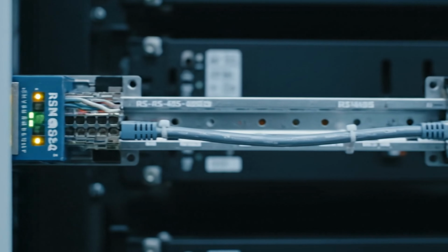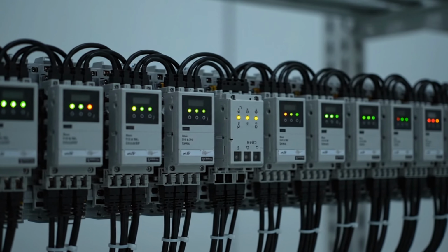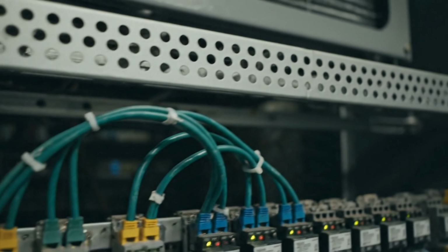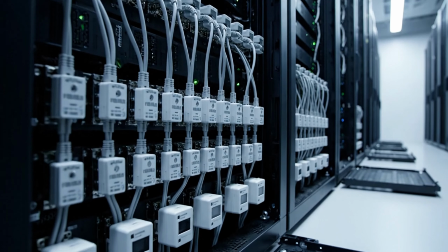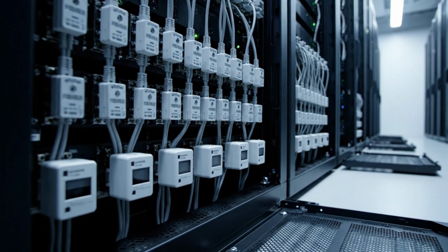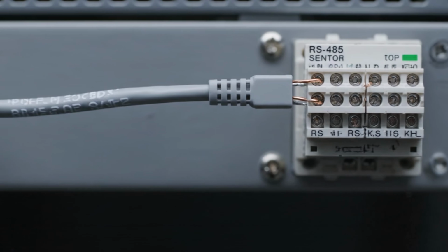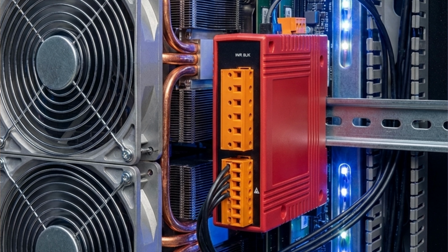So Modbus RTU is the one most people recognize. It runs over RS-485, it's simple, it's deterministic, and honestly, it's one of the most durable communication methods still used in industrial environments. I mean, there's a reason why so many cooling and environmental sensors still rely on it. Rack level temperature and humidity nodes, airflow sensors, leak detection modules, devices that are almost always deployed in large groups, tend to be built around RS-485 hardware. Even a lot of power meters used on cooling loads, like the kinds you'd see feeding data into a monitoring loop, still communicate over RTU because serial is stable, predictable, and extremely good at handling electrical noise.